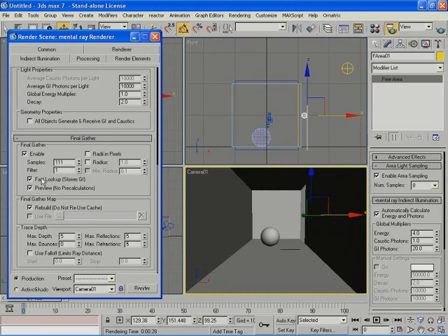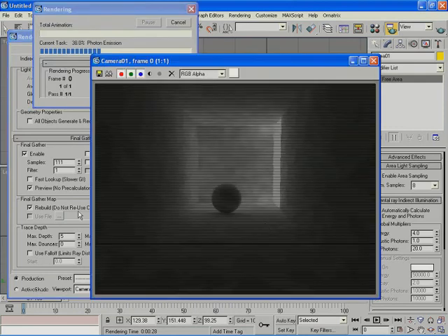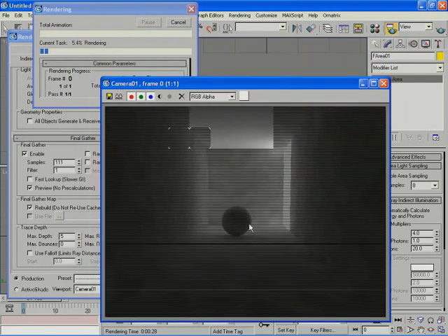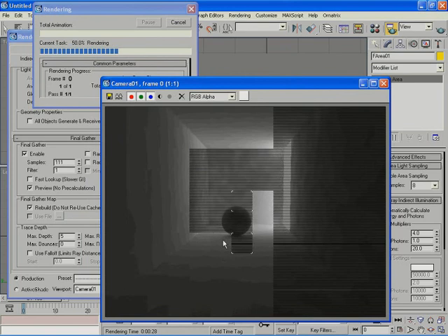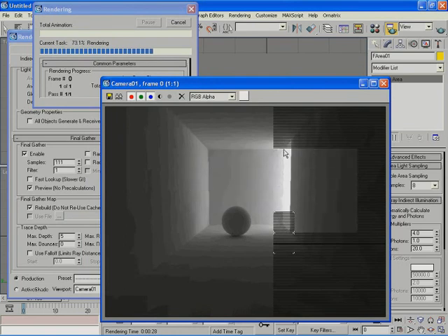And because I have preview on, I'm not going to have a final gathering calculation phase. It's just going to start to render from the beginning. So as you can see, the final gathering will remove any artifacts, and the result will be very nice with the combination of global illumination and final gathering. The last thing I need to fix are the artifacts, which are generated by the low samples from here. So let's increase the samples for now to 32 and increase the energy a bit more just to have a brighter overall scene. So I'm going to go to 8 and see what I get.